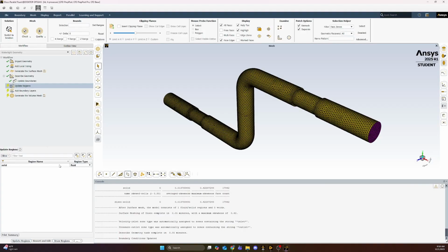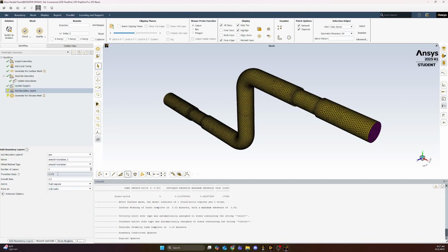And then this is asking for all of this mesh, is it going to be a fluid in these cell zones? And in this case, since we're not modeling any solid part of the piping, it would just remain fluid. All right, and then for this, I would like to have some boundary layers just because for any piping system, you want to see what's going on closest to the wall. But I believe these settings are good. I just up the amount of layers.